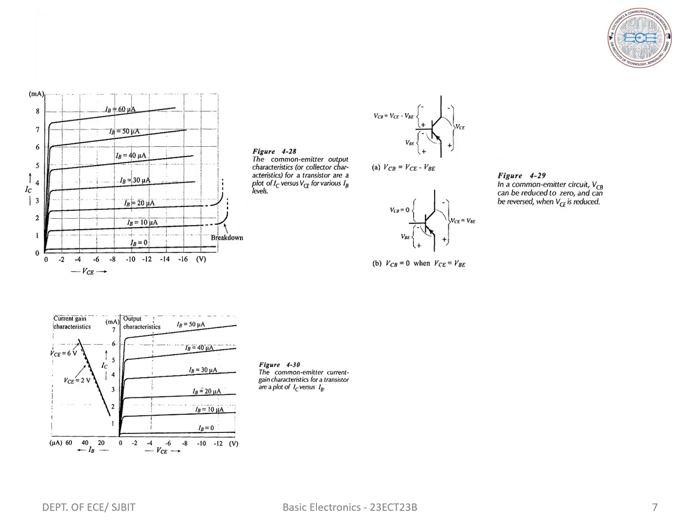Next, we have the output characteristics of a transistor in CE configuration. It is a graph of output current versus output voltage. The output characteristics curve is divided into three regions. They are cutoff region, active region, saturation region. Next, active region. In the active region, the collector current is beta DC times greater than the base current. Thus, a small input current IB produces a large output current IC.